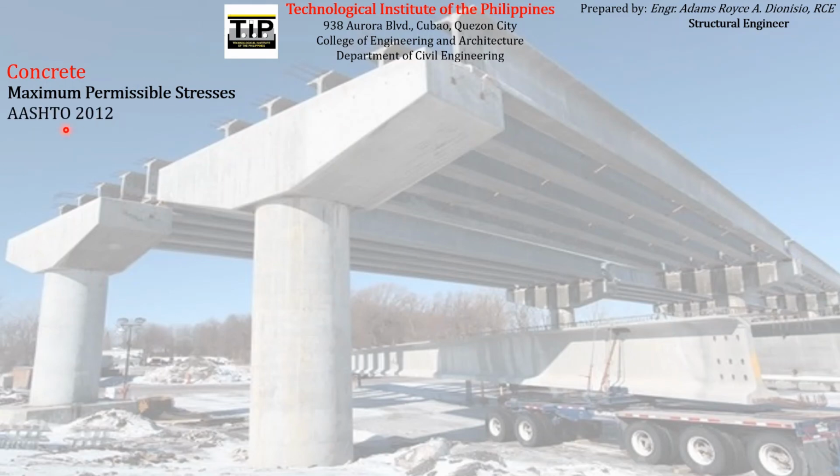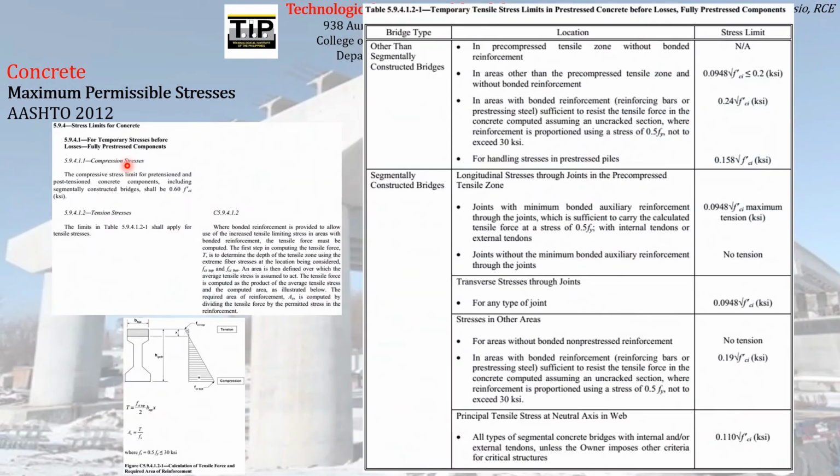If you refer to AASHTO, AASHTO has its own way to limit the stresses being experienced by concrete at different stages of pre-stressing. For example, before losses of pre-stress are experienced by the pre-stressing reinforcement, the code specifies these limits in compression for the concrete, as well as the limits for tension.